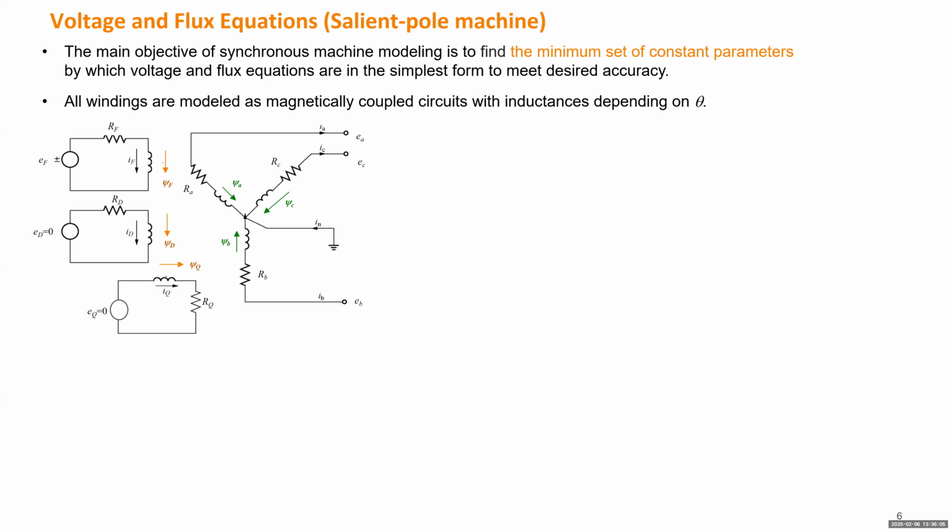Okay, so to model those windings, if we treat the stator windings and rotor winding as stationary, they don't move at all, we can borrow some ideas from transformers. For a two winding transformer, you just have one primary winding and one secondary winding. The two windings are coupled. They're not electrically connected, but they are coupled through the electromagnetic field.